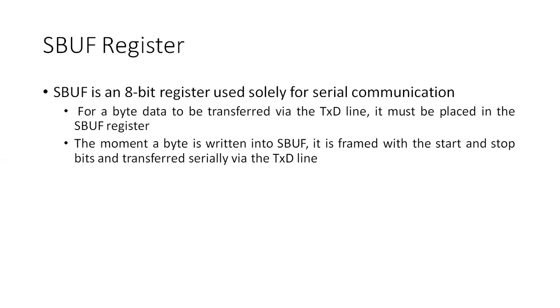Because we are seeing asynchronous communication, we are going to use 10 bits. The first bit is the start bit, following the start bit, 8 bits will be the data, and the last bit, the 10th bit, will be your stop bit. It will automatically frame the start and stop bit. Similarly, on the receiver side, it will eliminate the start bit and stop bit. It will understand only the data from D0 to D7.